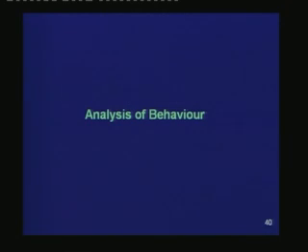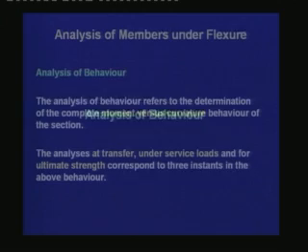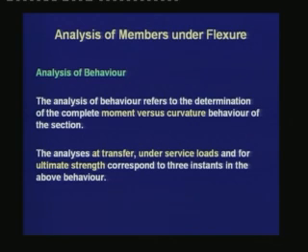Next, we are moving on to the analysis of behavior of a prestressed member. The analysis of behavior refers to the determination of the complete moment versus curvature behavior of the section. The analysis at transfer, under service loads and for ultimate strength correspond to three instants in the above behavior. Till now, for the analysis of members under flexure, first we had studied the analysis at transfer and service loads, which is similar and based on the elastic analysis, and then we had studied the analysis at ultimate.